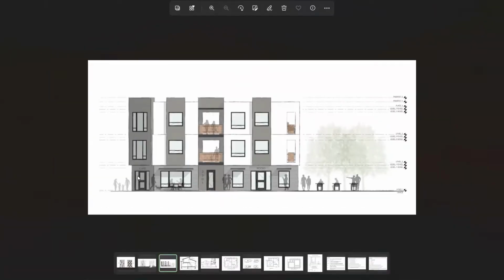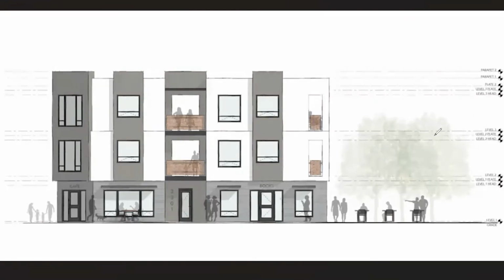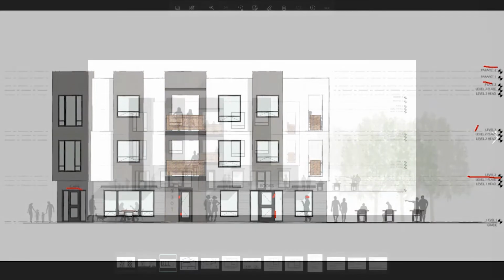Now, let us move on to another drawing. Yeah, this is an elevation. Again, one thing I like about this is that it has the different heights, or it's making a reference to the heights. It has some notes, and it's showing the human scale. It also shows the side on which the doors hinge, which is on this side and that side. This one will be on this side and that side. That's where the hinge is. This one isn't shown. The cafe door isn't shown. But generally, this is a good presentation, elevation drawing.